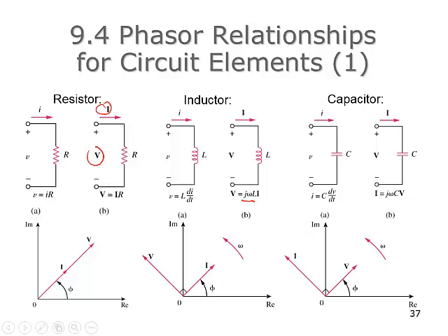How come they spin around? They spin around because it depends on what you're sort of thinking about. But when we did the phasor transform, we're basically starting with V of t equals some Vm times the cosine of omega t plus phi. Now, in the phasor transform, all we really need to know about is the initial phase. So we throw out the omega t part, right? So we say, well, that's the real part of Vm e to the j(omega t plus phi).